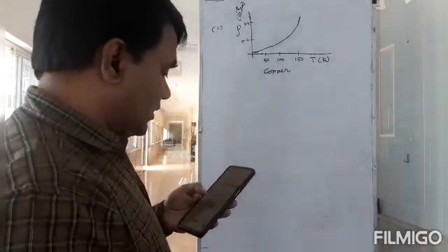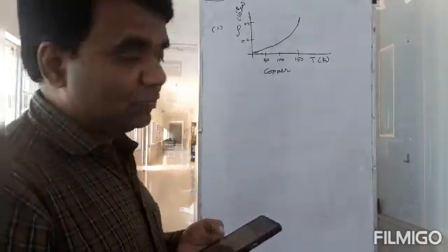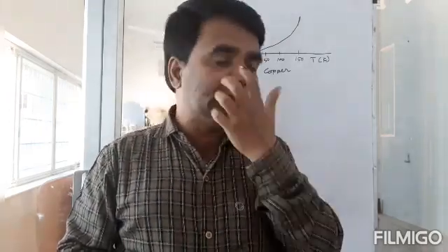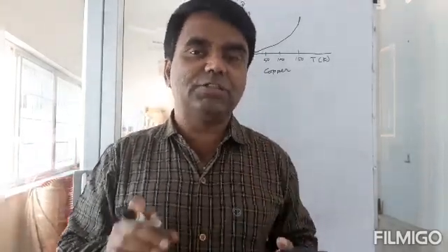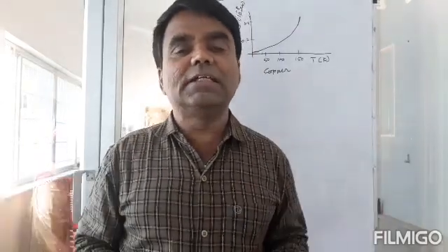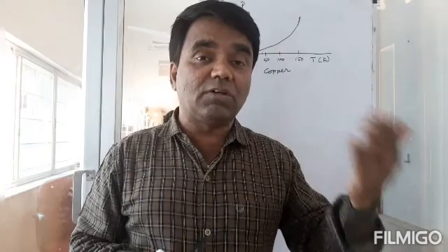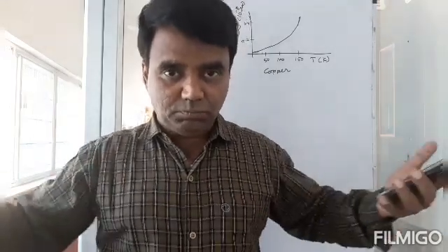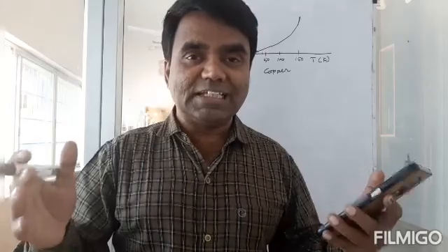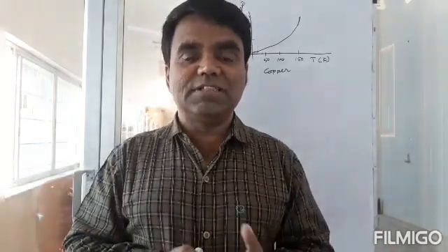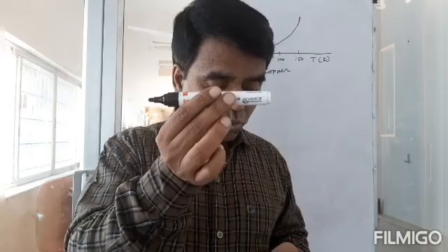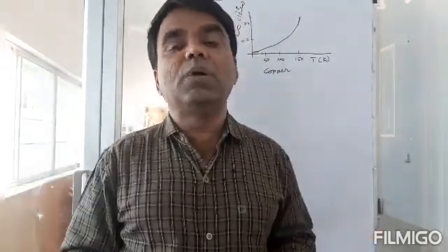And the second graph is for a material called nichrome. Nichrome is an alloy of nickel and chromium. It is used in circuits because the resistivity changes very slightly over a wide range of temperature. That's a great advantage because the resistance will not change. The resistance doesn't change for an applied voltage, so the current will not change over a wide range of temperature. So you can expect some stability. When you say this piece has a certain resistance, then that resistance will be the same over a wide range of temperatures.